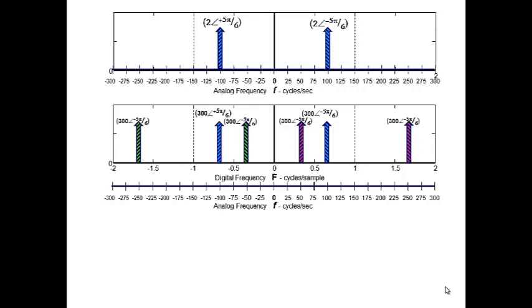Yeah. So the placement on the x-axis is the frequency of sampling. So this is frequency, and what was frequency 0 now becomes the center at every integer multiple of the sampling rate. Okay. And so I should also show copies centered around 2 and 3 and 4 and -2 and -3 and -4, but it's going to get too many arrows to confuse things.